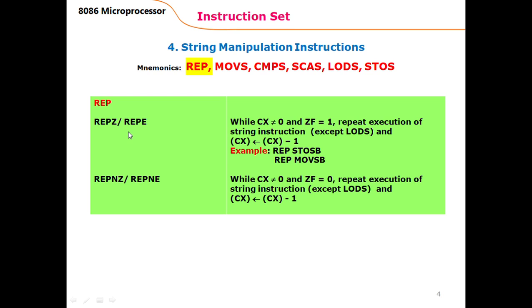They are alternatives of each other, so either of these forms can be used. So there is a string instruction followed by this REPZ or REPE. The instruction that follows would be repeated. Its execution is repeated as long as the counter value is not equal to 0, and as long as the zero flag is 1.